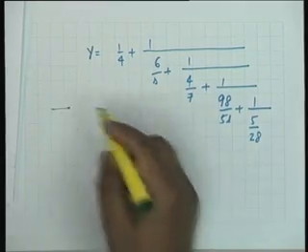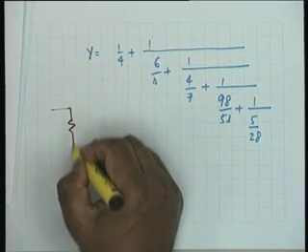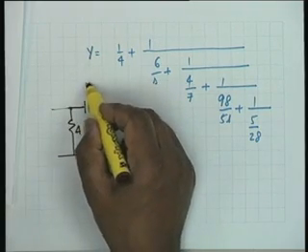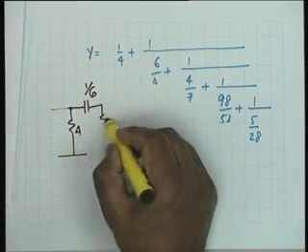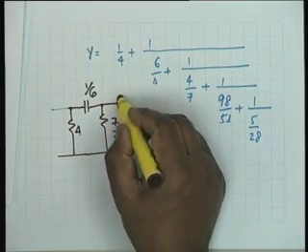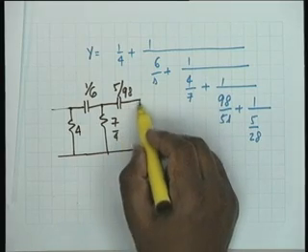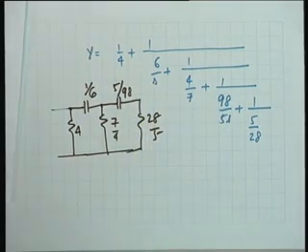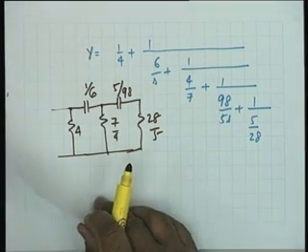So what we get is our network becomes a resistance of value 4, then a series capacitor of value 1/6, right? Then a resistance of value 7 by 4, then a capacitor of value 5 by 98, and finally a resistance 28 by 5. It's done. We have done Cauer 1, Cauer 2. All the 4 canonic forms have now been done.